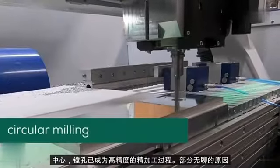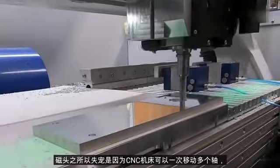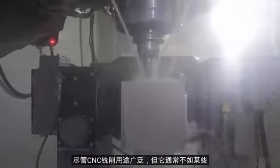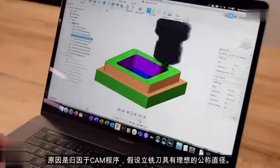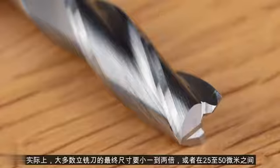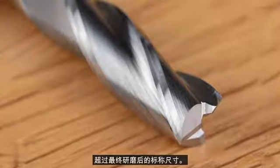Part of the reason boring heads have fallen out of favor is because CNC machines can move multiple axes at once, making it possible to mill circles and complex profiles. While CNC milling is highly versatile, it is usually not as accurate as some of the processes we've covered, especially when it comes to holding a size tolerance. A lot of the reason comes down to CAM programs assuming a perfect nominal diameter for an end mill. In reality, most end mills end up 1 or 2 thou, or between 25 and 50 microns, smaller than their nominal size after final grinding.